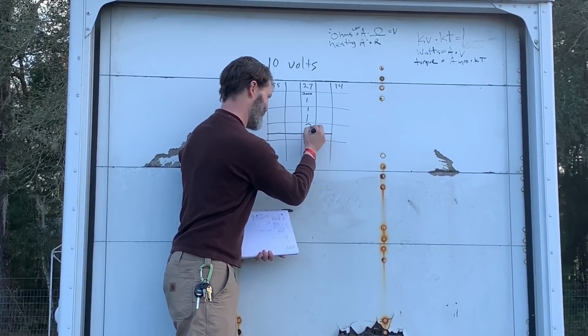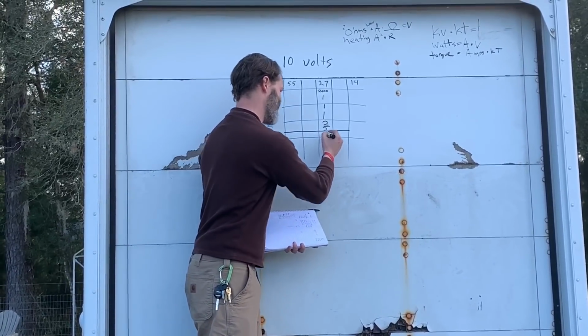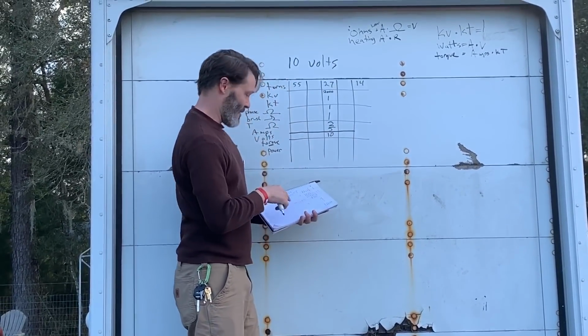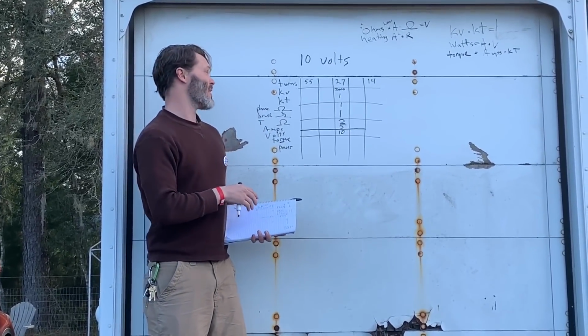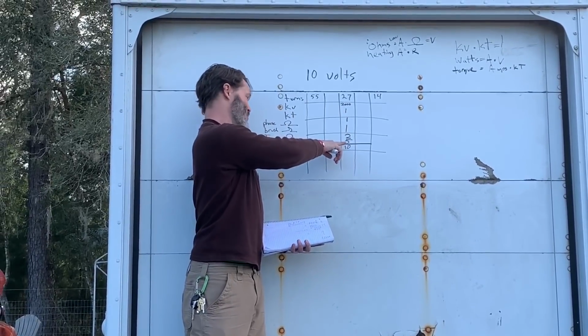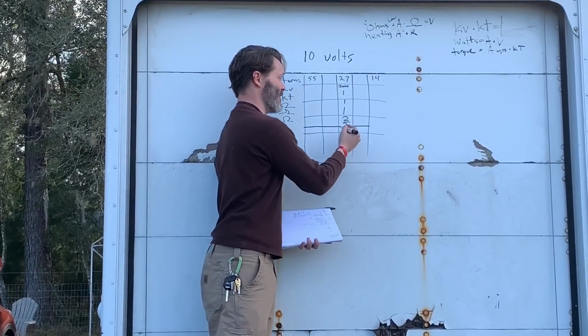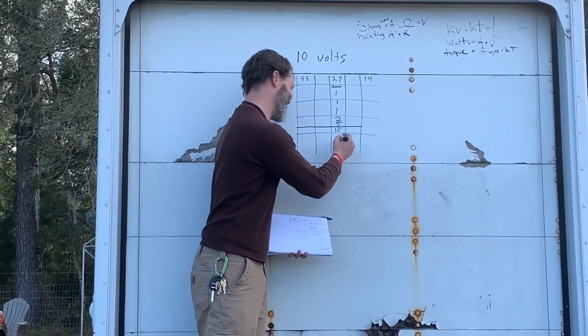These are going to be the numbers that matter. Now we've got volts. Oh, I already had volts on here somewhere else. We'll just put it down again. Now, since we're not using units of torque specifically, we can just literally multiply the torque constant up here, 1, times our amps, and we get our torque output down here. So it's going to be 5 times 1. Everybody, 5? 5.